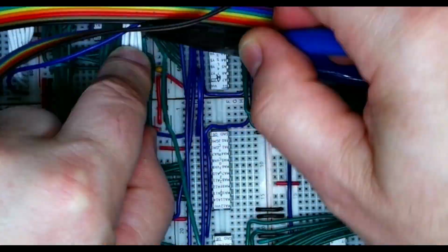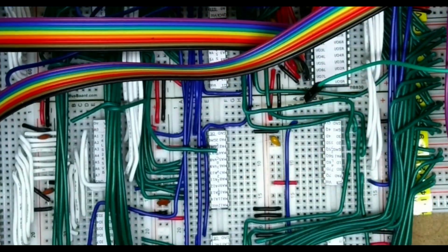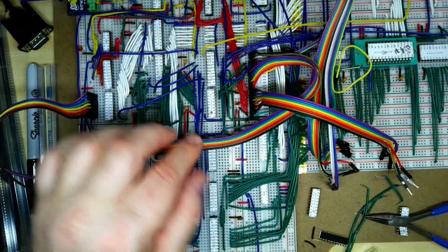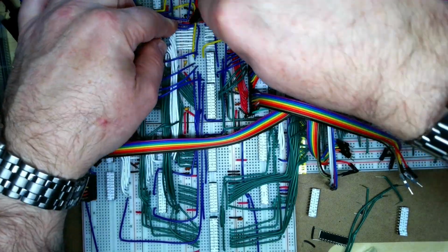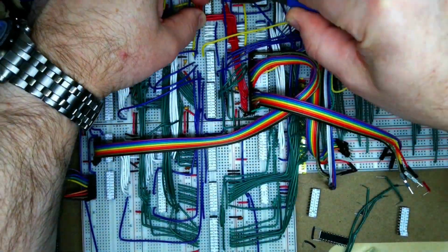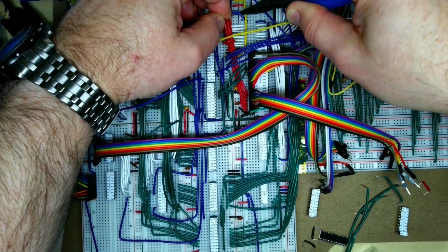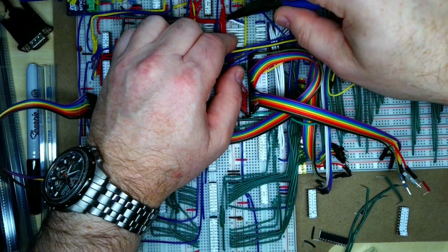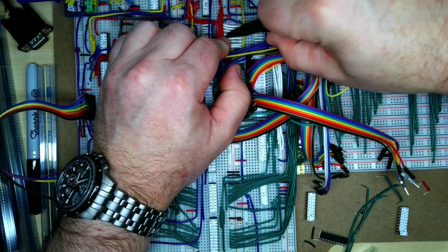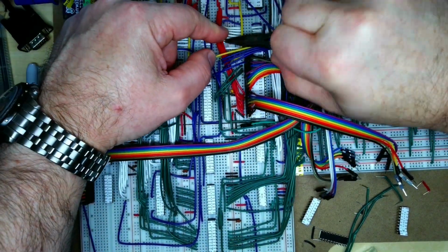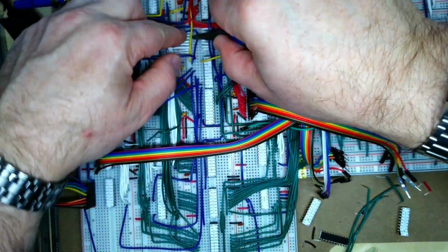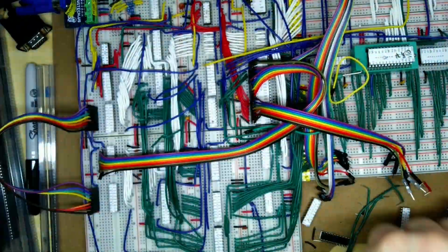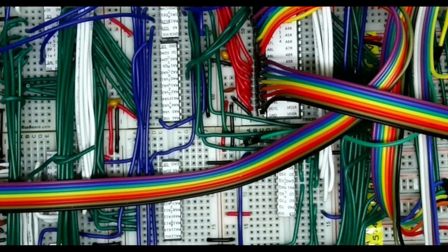Now we also need to put in the address 7 line, which is actually now handled by this lower chip, so we just need to make sure we've got the video address line 7 in there. Now we need to make some space up top here for moving up the PLD, which is just below the data lines there. So we're moving the data bus up by 1 hole and having to shuffle those wires over on the right hand side, and the top blue wires, the read write as well. Just shuffle those other wires up, so that should allow us now to move that chip up, and we also then shuffled all the wires up along with it as well.